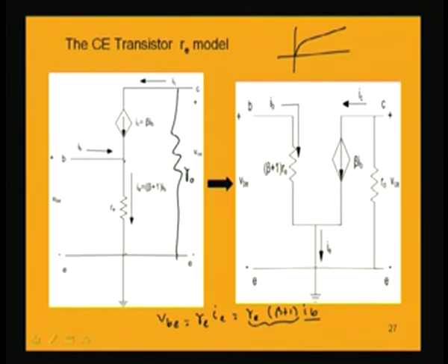is now reflected as (beta plus 1) RE, but you see the current, this is the base current, is the same current flowing in the resistance as well as the starting or the input current. So, this current IB is flowing through this resistance meeting here with the current which is from the collector, this is beta times IB. So, IC plus this IB is now IE which is flowing to the ground. So, now at this point both IB plus IC are meeting.